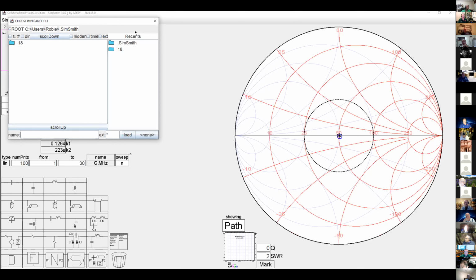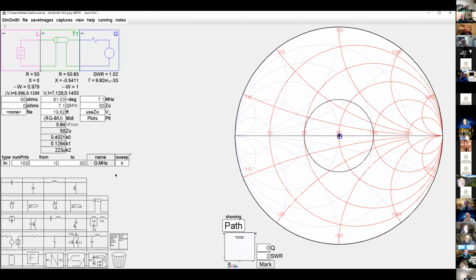It can be imported here. And then you can use this function down here called sweep, which I have turned off. You can put in the same frequency values and the same number of points that you have in your EasyNet file. You can turn sweep on, and it will put your antenna in there on any frequency between any frequencies that it has impedance values for. Incredibly powerful in that respect as well.